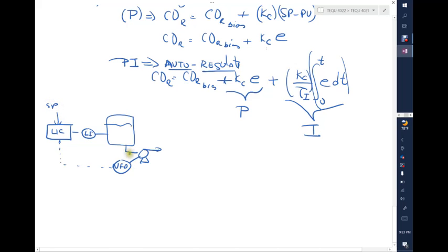This system is not good for a PI controller. You are better with a proportional controller on here. It's better with a proportional because this system does not auto-regulate, so better use proportional. If the system has a good steady state, at least for a steady state based on the variable that you are manipulating, then definitely a PI will work okay. And that's what I'm saying.